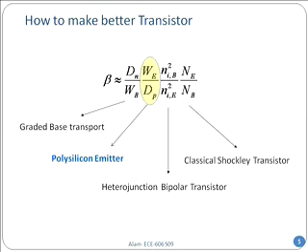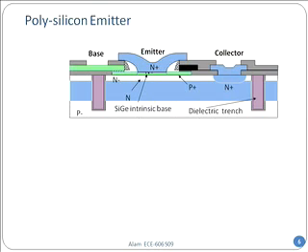And let me start by talking about the polysilicon emitter and the innovation that went with it. Now, all modern transistors have a polysilicon emitter. The wing-shaped blue region that you see at the top is actually polysilicon. So polysilicon means that instead of growing it at high temperature, where the material is single crystalline, do you remember all the atoms in their places, the Bravais lattice, do you remember those things?